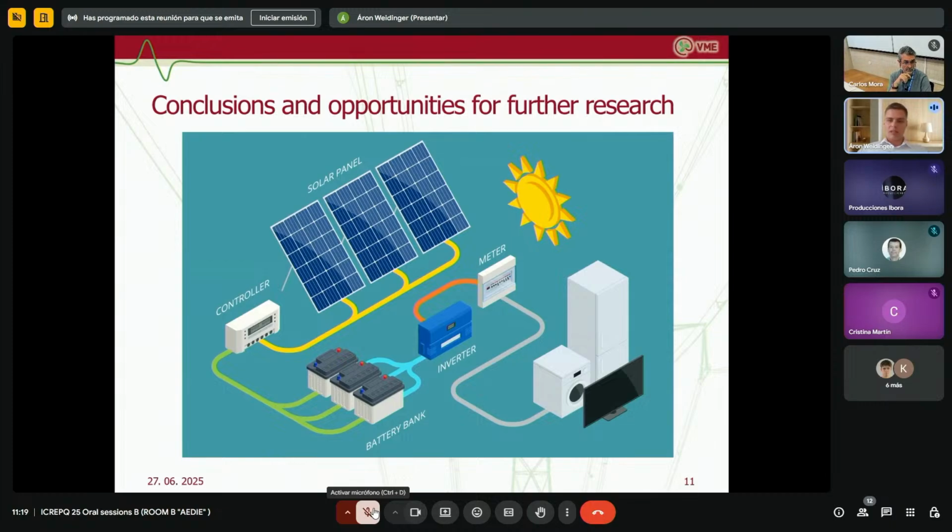Going forward, we plan to test adaptive HVDC control strategies in order to step outside of the limitations of this modeling approach. For example, making the power transfer responsive to local frequency or angle deviations. And this may offer the improvements we hope to observe, but will require deeper modifications in the model.